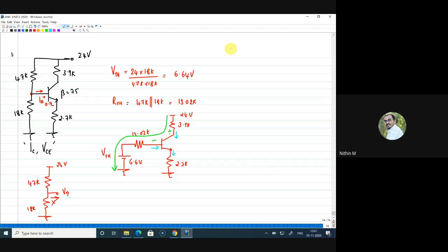So Anushka, thank you for your response. Make a point here. This is to everyone. Whenever you are starting with any BJT based problem, if there is a chance that the transistor will be in the active region, or sufficient potentials are connected to collector and base to make it active, you can go ahead with the assumption that the transistor is in the active region. You can always go with the base loop, because when the transistor is in active region, you have VBE voltage of 0.7.